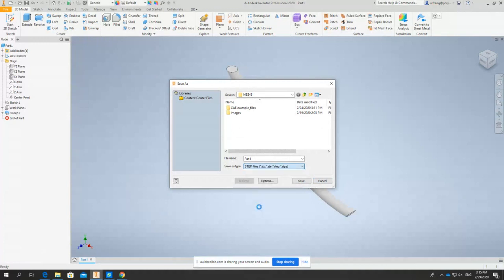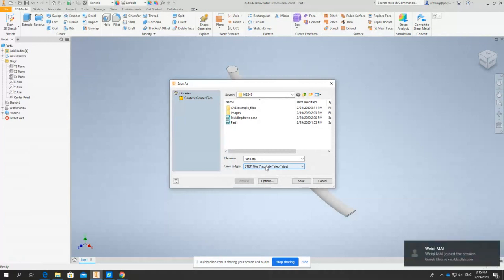STP is that file. When you use some simulation, we need to save three files. One is Parasolid, STEP, or IGS. We just got three files that you can import the geometry from: SolidWorks, AutoCAD, or Autodesk Inventor, CATIA, because those software have got other file formats, not just the Inventor part or SolidWorks part file. You can file save as another file format.